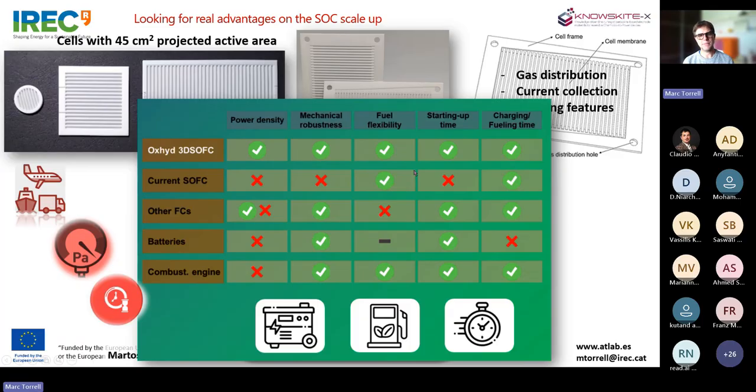Here we have a table, very conceptual, of the advantages of this new technology. We call it Oxide 3D Stack because Oxide is the name of a new spin-off that we are launching with this technology for fuel cell applications, where we can increase the power density, we can increase the mechanical robustness, we keep the advantages of the solid oxide fuel cell technology in the fuel flexibility and fueling time compared with batteries, okay, but we also improve the starting up time, which is one of the main drawbacks of this technology.